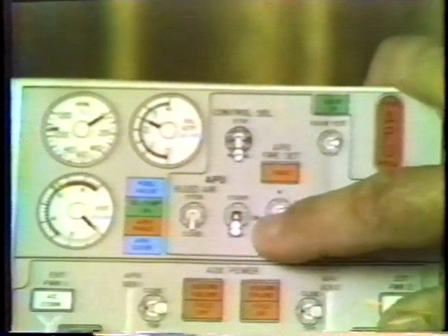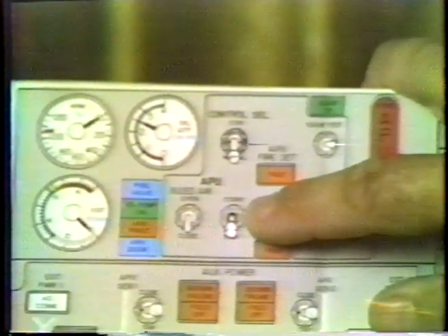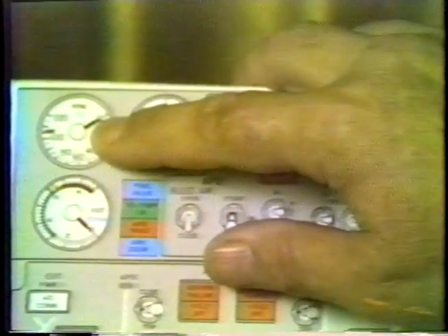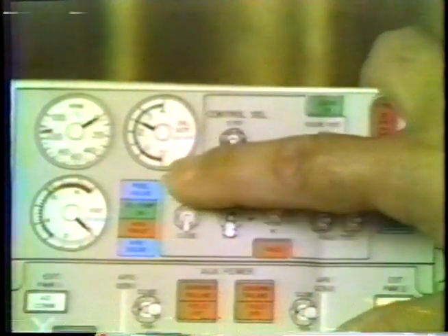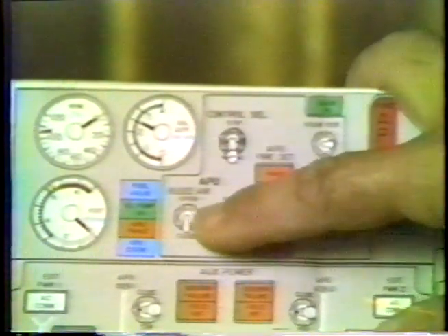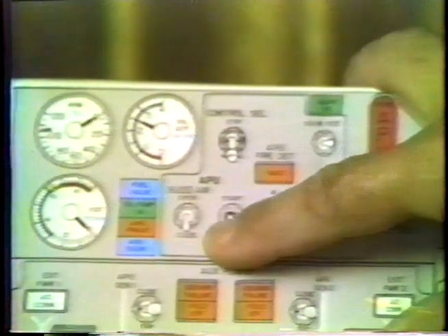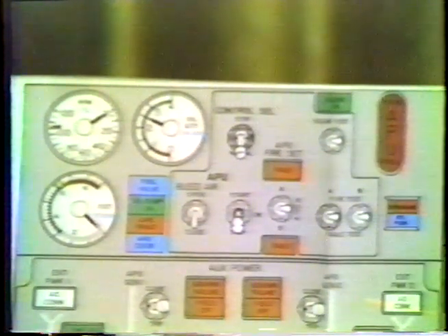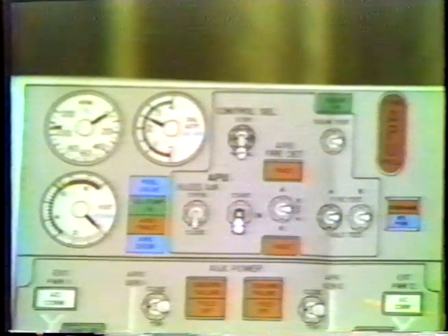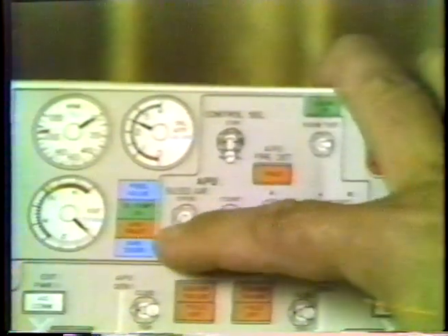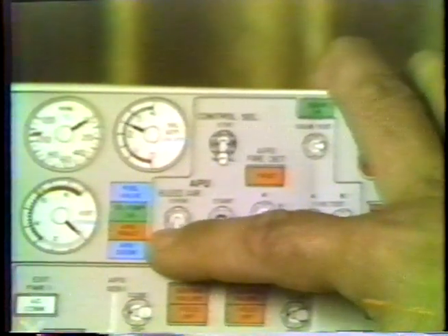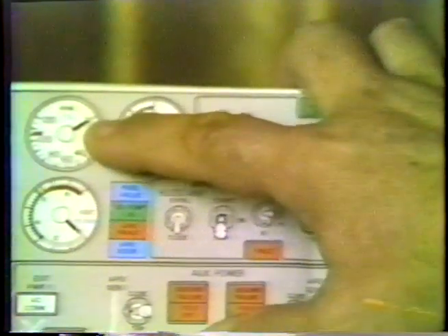Upon holding the switch to the start, which is spring-loaded, you will see RPM, and then after a short period of time, EGT. Generally, during the start, the oil quantity will drop. If it drops into the red band, the start switch should be placed to stop immediately. There are quite a few items that will automatically shut down the APU, but in every case, anything that automatically shuts down the APU, the fault light will illuminate. And of course, you would expect to see the RPM and the EGT drop also.